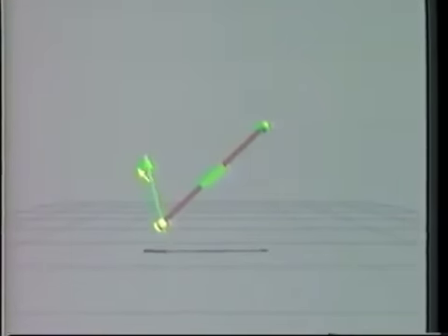When the endpoint is selected, it highlights purple, and the cursor changes to indicate that we can now select the to object. Note that objects only highlight purple when being linked together with constraints. We then select the ray, and it too turns purple. Now the cursor indicates that the system is waiting for user confirmation. We click again with the mouse to confirm this constraint. Now the endpoint is linked to the ray, and it turns yellow to indicate that it has been partially constrained.